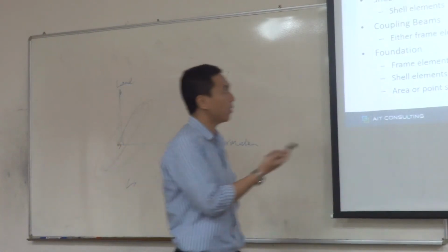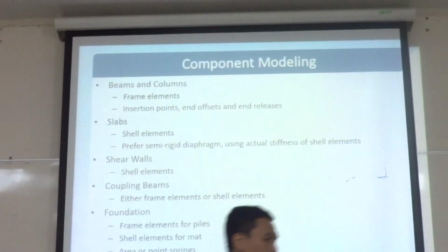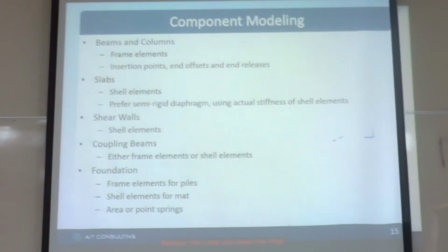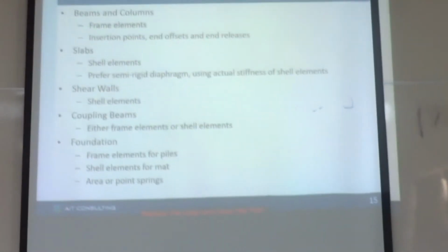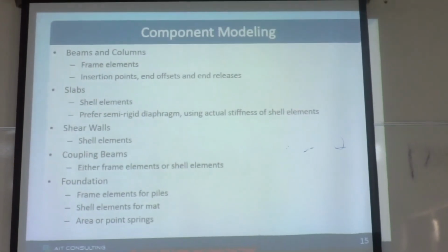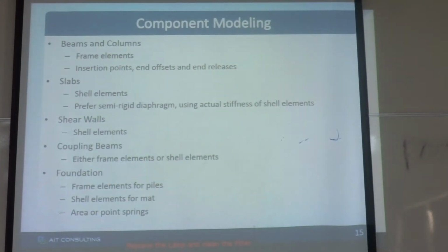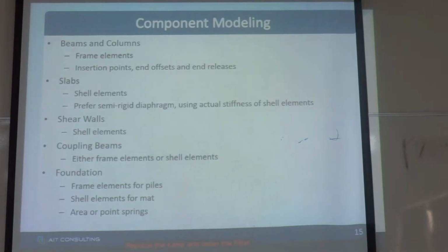And releases are, sometimes we want to connect the beam with the column with a moment release pin connection. If you want to use that one, we have to release the moment in the model.